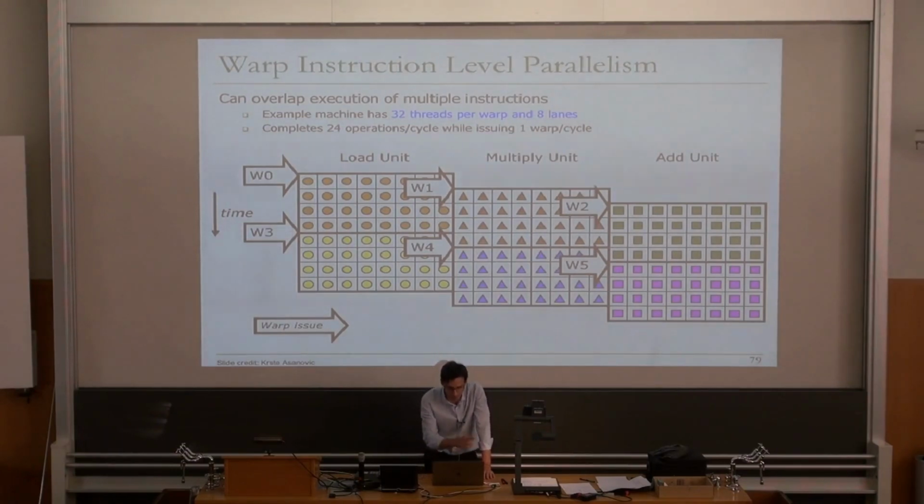One thing to keep in mind is that the warp scheduler, the unit in charge of getting the instructions and issuing them on the execution units, is not going to issue, for example, a multiply operation for warp 0 until the load operation for warp 0 has completely finished.